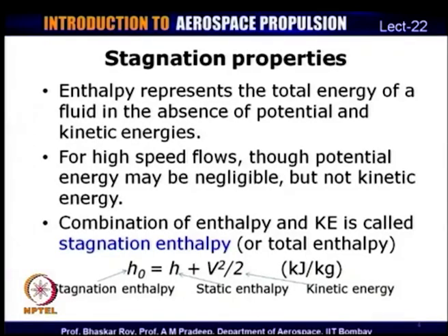We know now that enthalpy basically represents the total energy of a fluid in the absence of potential and kinetic energy. This comes from the first law of thermodynamics. When we take up this property of enthalpy at high speed flows, potential energy being negligible may still be valid, but not kinetic energy. So, we have to take into account the changes in kinetic energy.